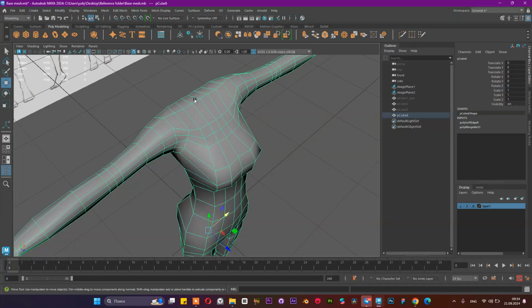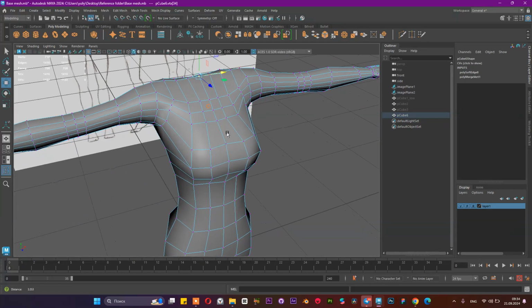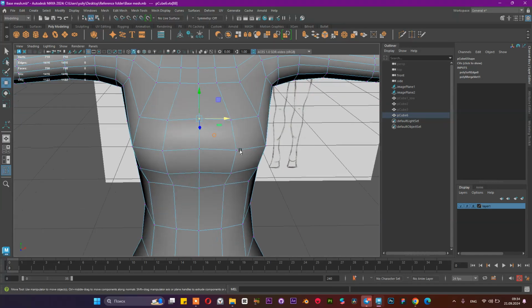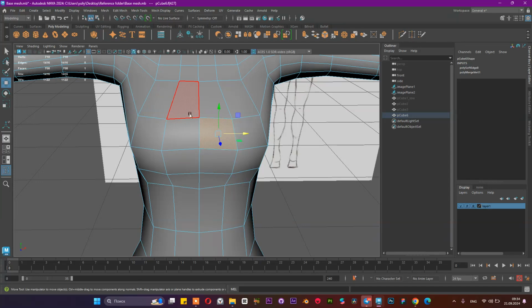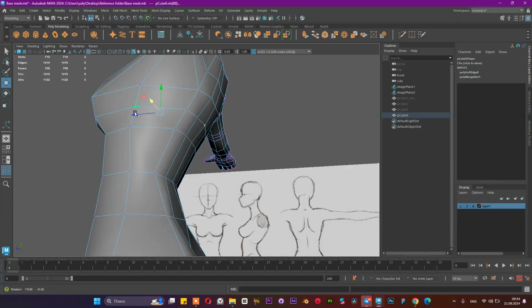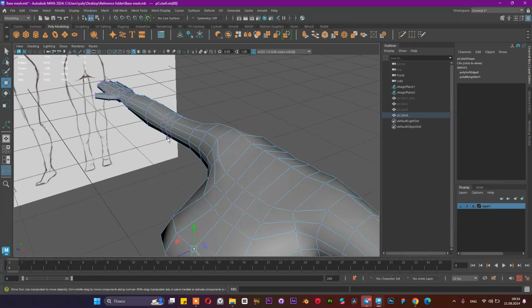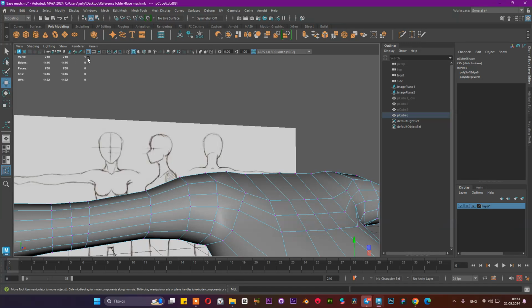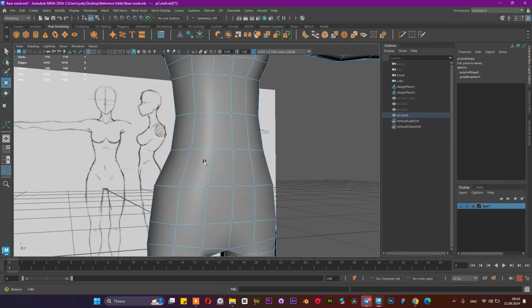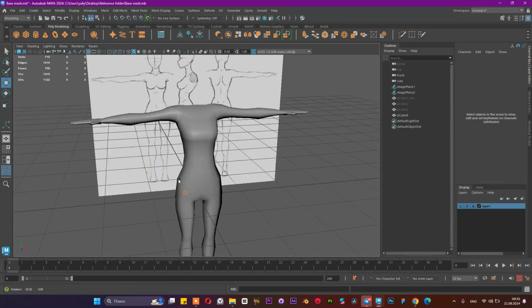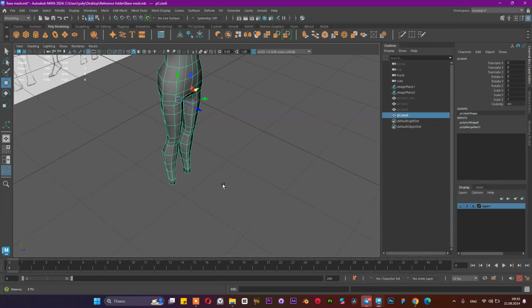The main purpose is to keep the model view without two vertices on one side. You can check by selecting, and the polygon count shows you how many vertices are in one place of the selection. If it's two, you can merge them one by one. If it's aligned, you can merge the whole model. I think we can continue with the feet.